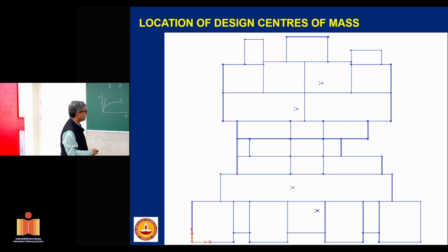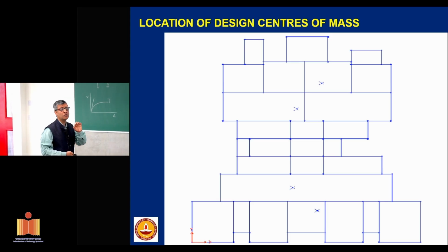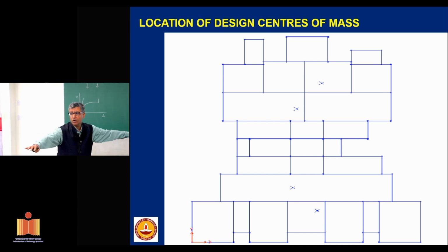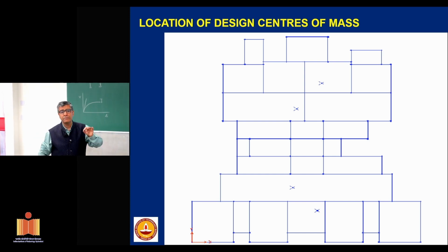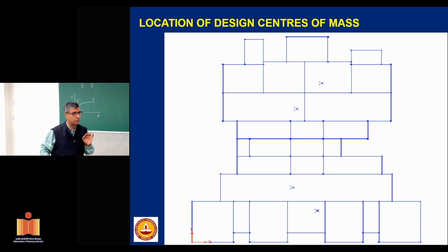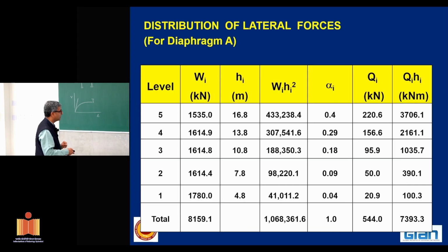Coming to the lateral load analysis, we define what is called center of mass, or to be specific, design center of mass. That means the force is actually distributed throughout the floor area. But for convenience of analysis, we apply the force at a certain node, which is called the design center of mass. I will skip some of the details.